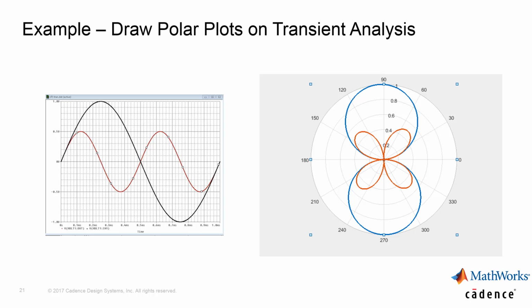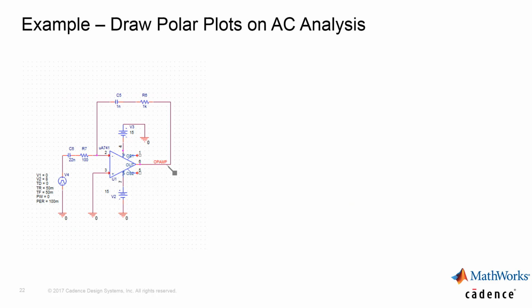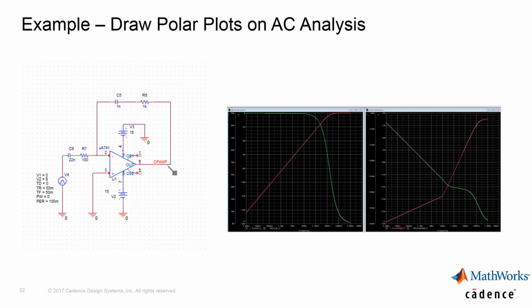In this example, we are showing how you can draw a polar plot on the transient analysis running in PSpice. So in other words, on the left-hand side, you're seeing a transient analysis waveform in PSpice. And on the right-hand side, we are showing how you can view the same data in a polar plot in MATLAB environment. Next example is more on the frequency analysis side.